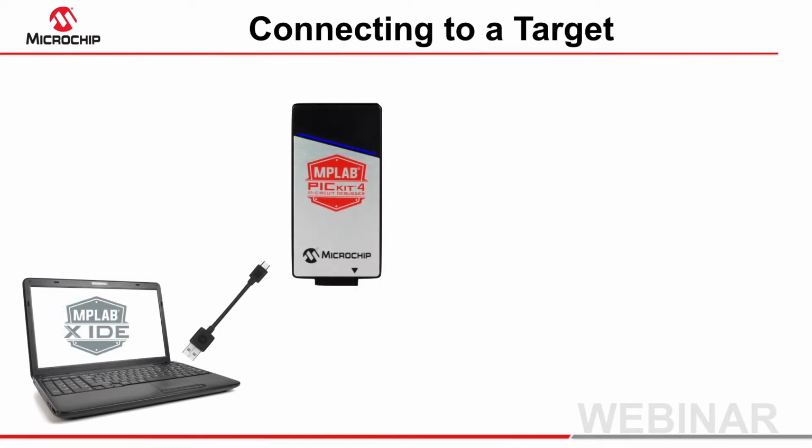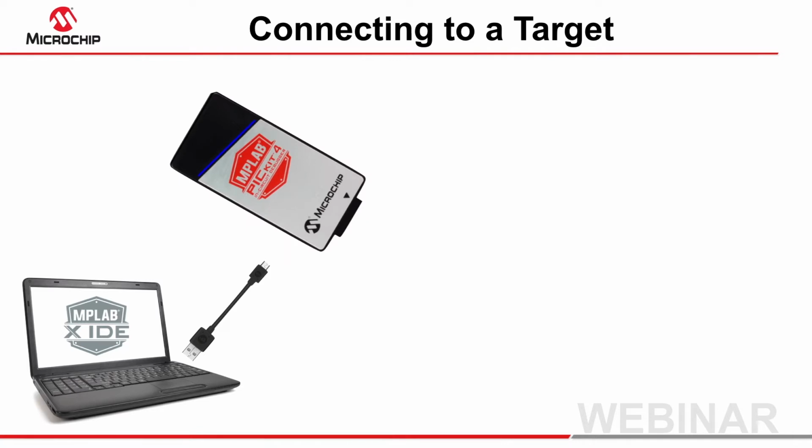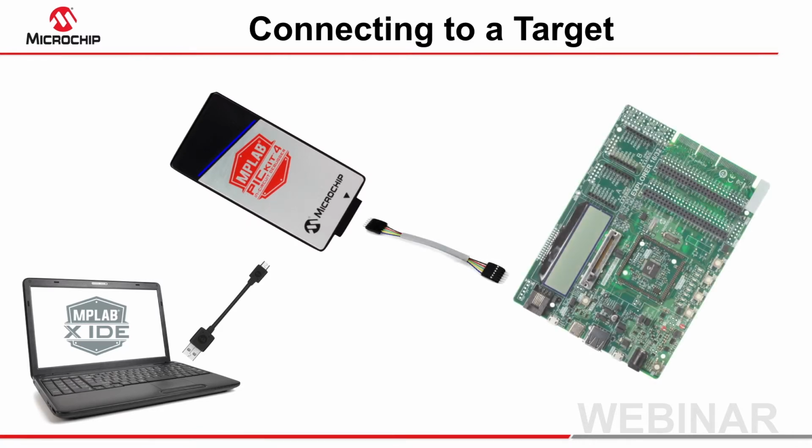If you are using a compatible Microchip development board, you might be able to simply connect the PICkit to the board's ICSP connector. The PICkit 4 uses an 8-pin cable, but you can still use this to connect to boards that have the older 6-pin connector. Just leave the last 2 pins of the cable unconnected.